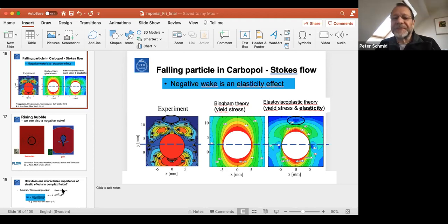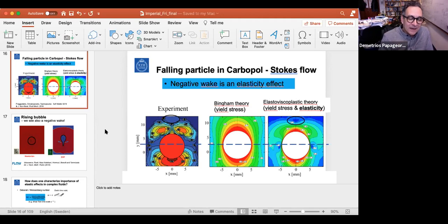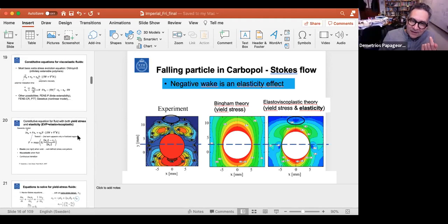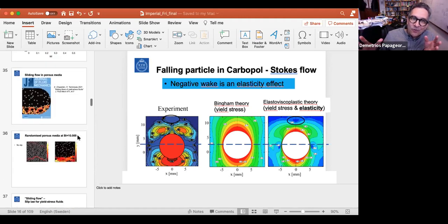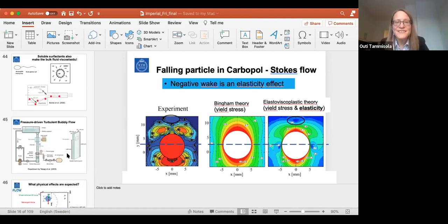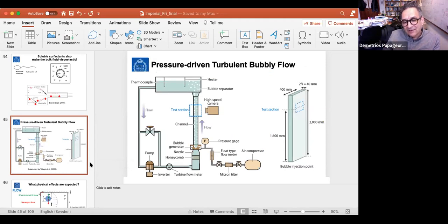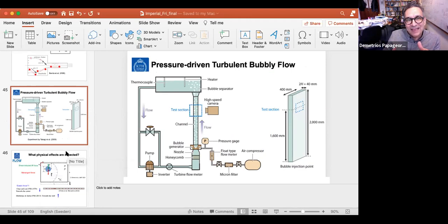Good. Any other questions? Yes, I have one. The experiments by, was it Tagaka or Takagi? Yeah, Takagi. Are those initially viscoelastic fluids, or is it water with lots of surfactant? It is water. This was just a motivation from my point of view, that when you put surfactants in the bulk, the fluid becomes a little bit viscoelastic. So that's why it makes sense to include this effect in simulations. Yeah, but that's my question actually. If you want to make it viscoelastic, how much surfactant do you need to add? And if you add beyond the critical micelle concentration, then you're going to get phase changes and all sorts of things that are not modelable the way you did them.